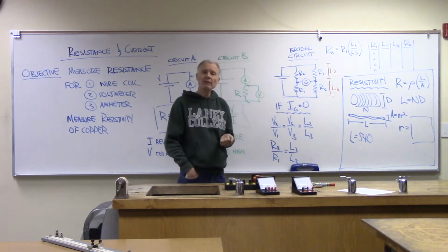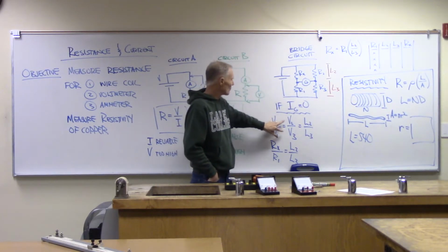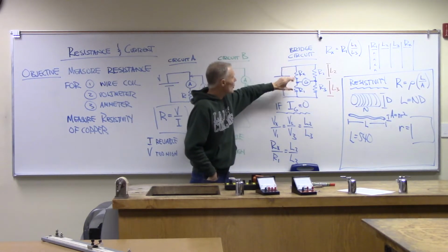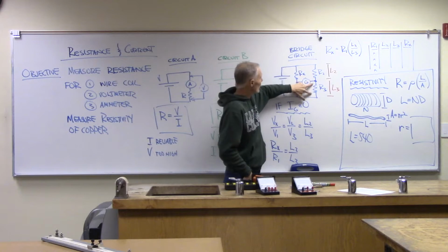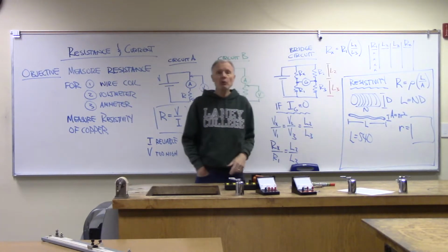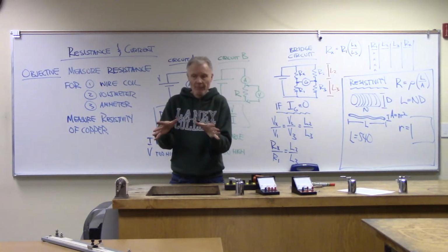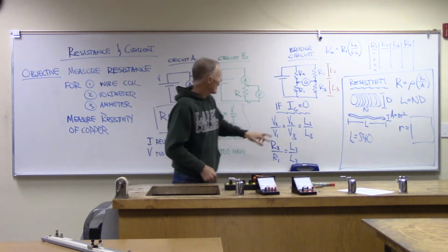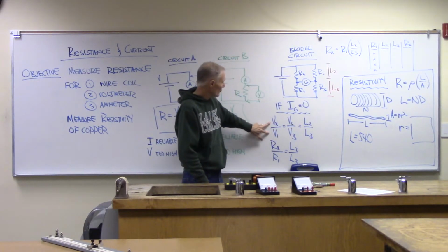The voltage is being divided up with the same ratio. Now, if Vx over V1, that ratio, matches V2 over V3, well, this ratio is going to be the same as L2 over L3. So that means that I can measure the length of this precision resistor wire, and that is going to tell me what the ratio of these voltages is equal to.